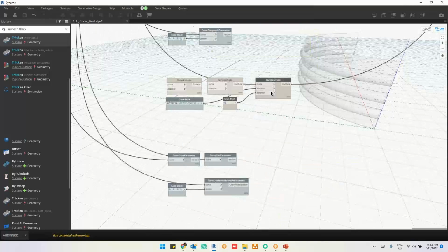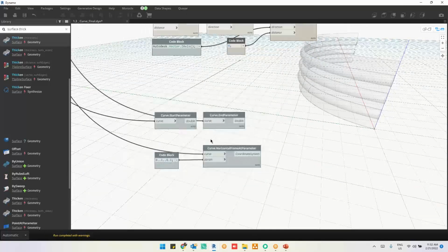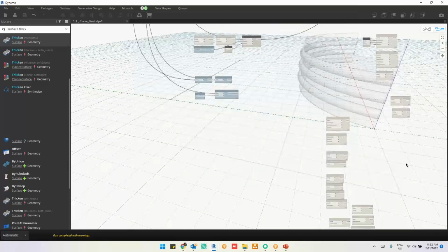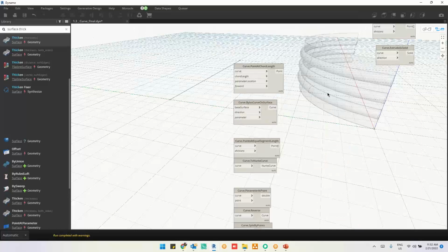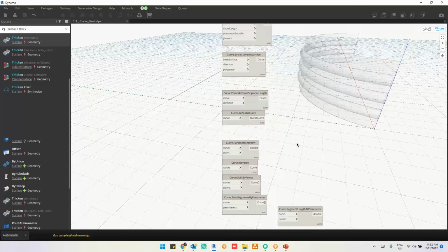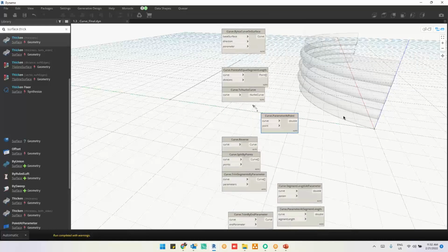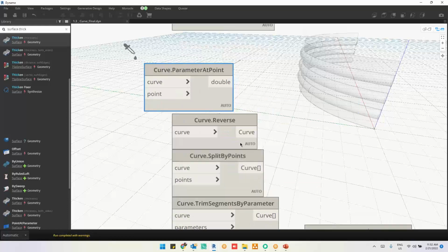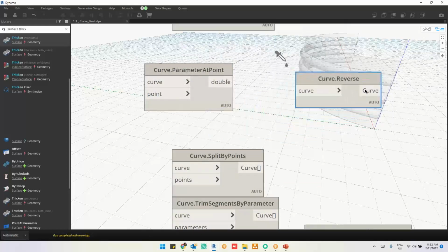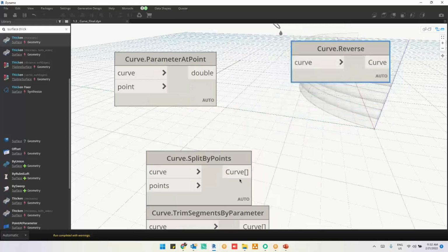It's not that tough to remember. Okay. Well, we have some sort of notes that you guys can play with. Okay, I'm going to share them with you. These are not regular, like we have already played with parametric point. Curve dot reverse. So if I want to get the reverse direction, there's curve dot reverse, curve dot split point. Let me show you a few others as well. Poly curve, NurbsCurve.